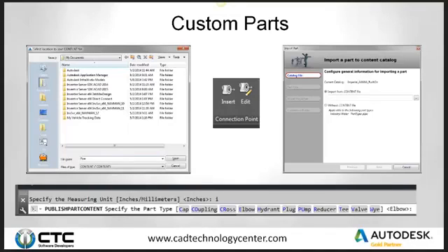And after I define that, by default it's inches. One of the previous things was, is it in inches or millimeters, not feet. Even though Civil's set to be feet, you want to define everything as inches. So when you build this, you build it in inches, not as feet. And you'll go on.